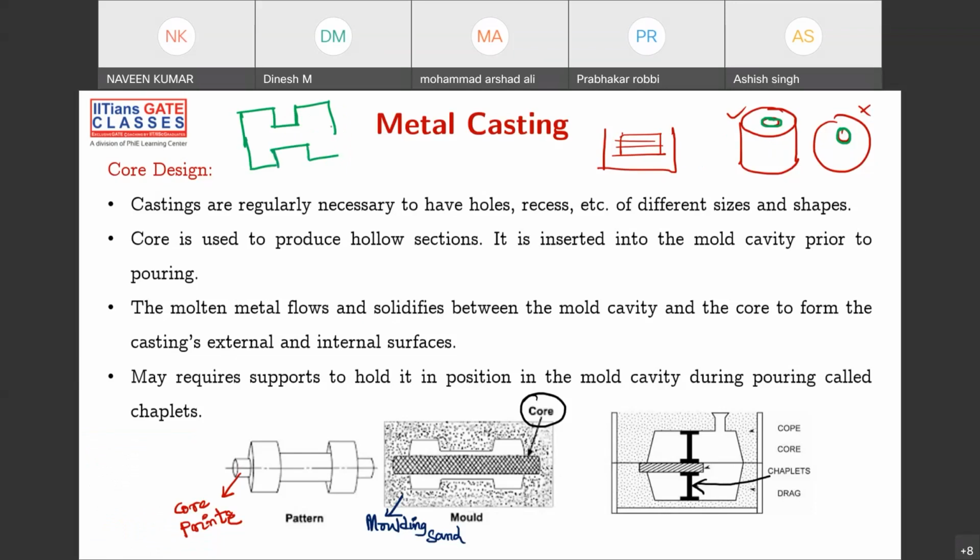Okay, so let me take another figure. Okay, sir, I'll put the core like this. But after pouring liquid metal, core material is having some density, and the liquid metal you're pouring is also having some density. Due to density differences, this core might float up or might come down. We don't know. It can't be exactly hanging in between, right? So to make sure that this core is at exactly the same place, you have some protrusion like this.